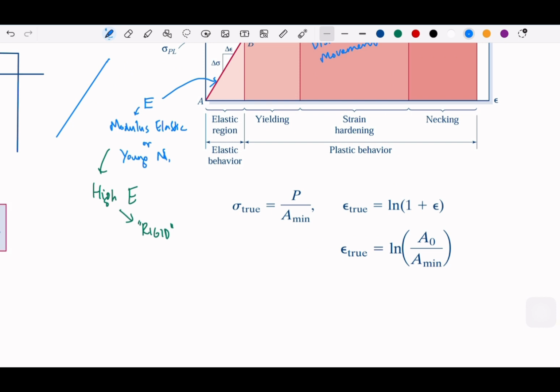We can write using this, or we can write using the surface area or the cross section. So we have now the true stress and the true strain. But the previous models still work for design. At some point it still works for design because we are not going to take the whole graph itself. But if we want to know the true values, then we are going to need this area that changes during necking. Now let me zoom out a little bit.